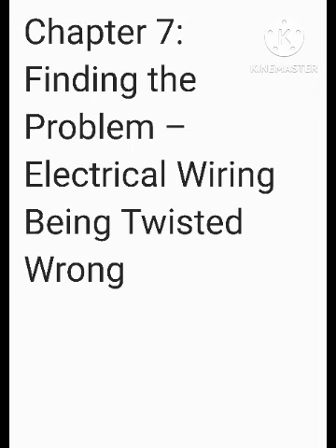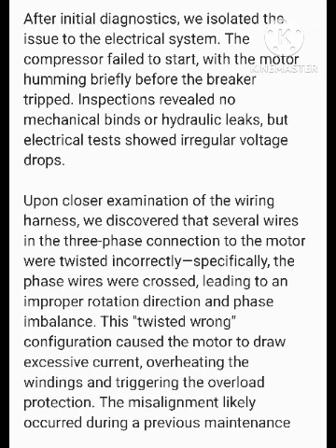Chapter 7: Finding the Problem: Electrical Wiring Being Twisted Wrong. After initial diagnostics, we isolated the issue to the electrical system. The compressor failed to start, with the motor humming briefly before the breaker tripped. Inspections revealed no mechanical binds or hydraulic leaks, but electrical tests showed irregular voltage drops.